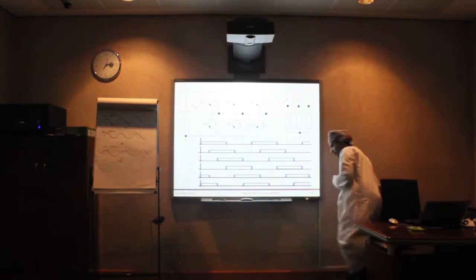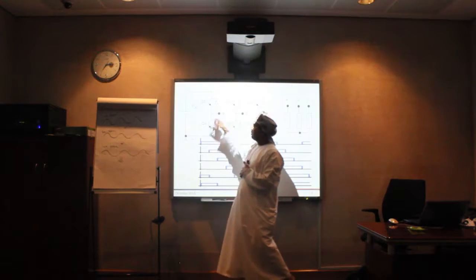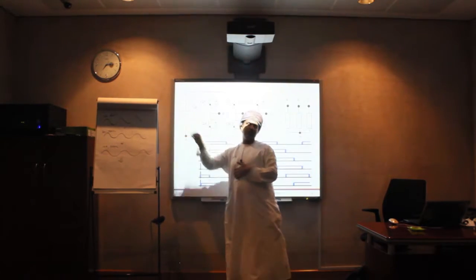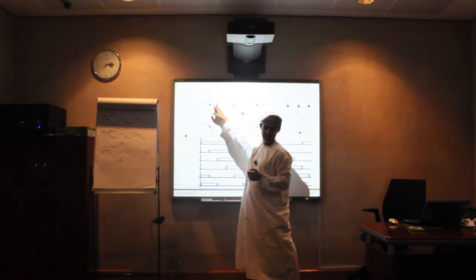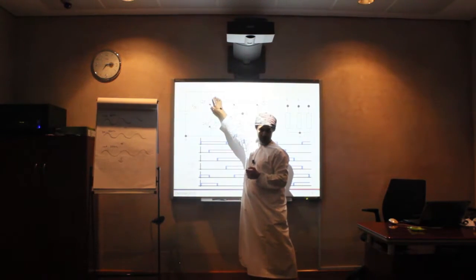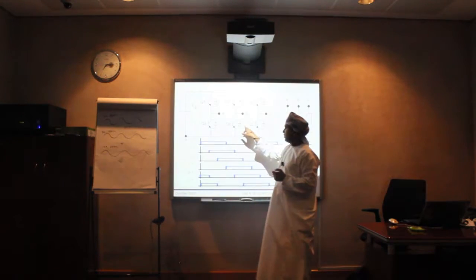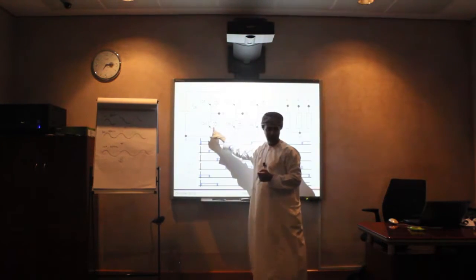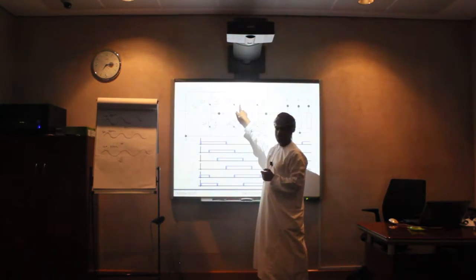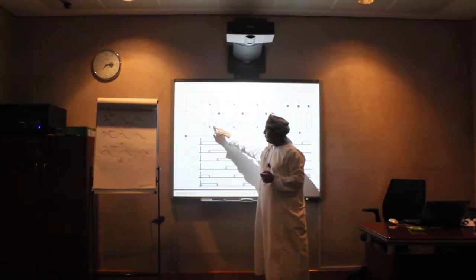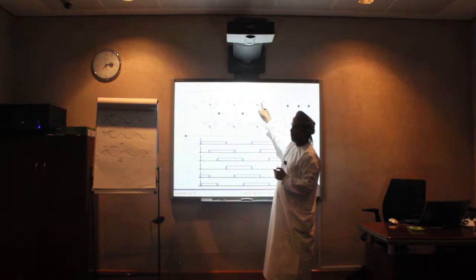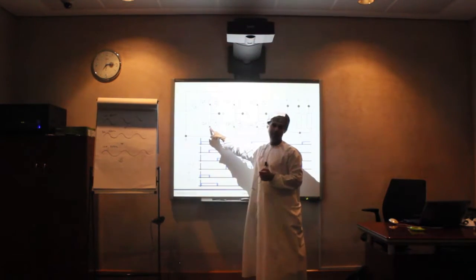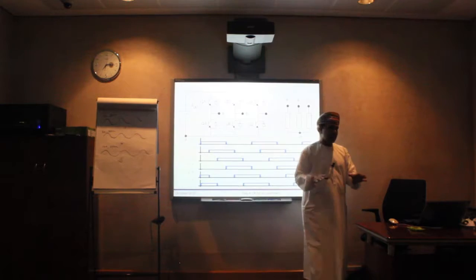For example, if you turn on this one and this one at the same time, you will get a short circuit, right? So the top one here should operate with these two, but not with this one. And the same thing, this one should be operated with Q4 and Q2. And Q5 should be operated with Q6 and Q4. So this is how we arrange those.